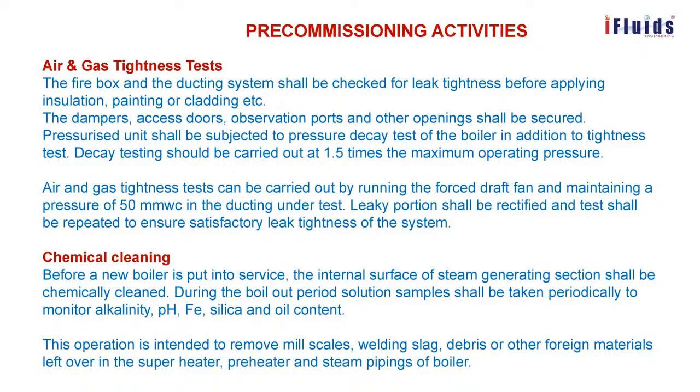For that, the chemical cleaning should be taken care of, with sodium hydroxide, sodium carbonate, trisodium phosphate and detergent. All these are mixed according to the ratio given for each and every boiler. Generally, you can say 0.5% of sodium hydroxide, sodium carbonate 0.3%, trisodium phosphate 0.3% and detergent 0.05%.